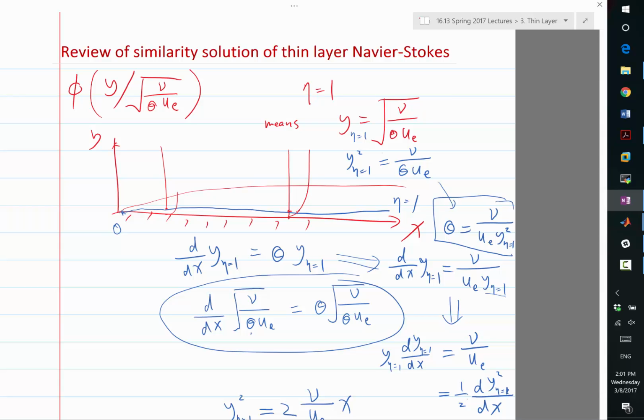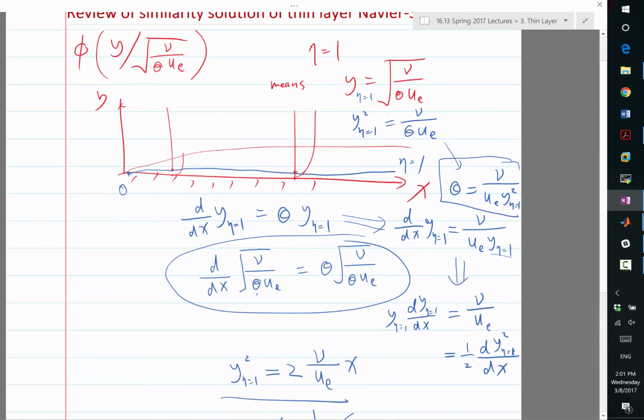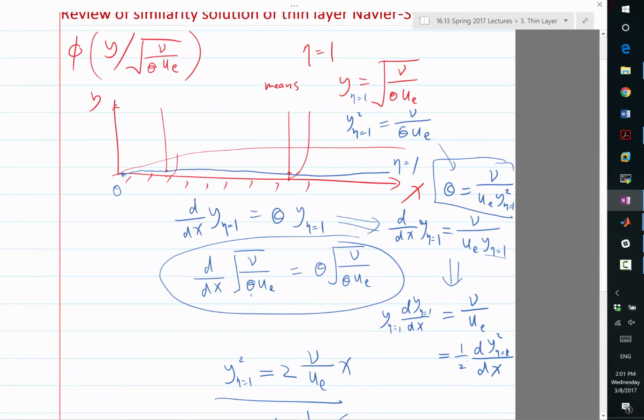One case is a viscous flow with a boundary layer with a displacement thickness defined this way to be a certain function of x. In the second case, the outside streamline is the same if I have an inviscid fluid with no boundary layer at all, but the wall is displaced by a certain delta y that is exactly the same as the displacement thickness of the boundary layer in the first case. So the outside streamline is going to be exactly the same for these two cases.